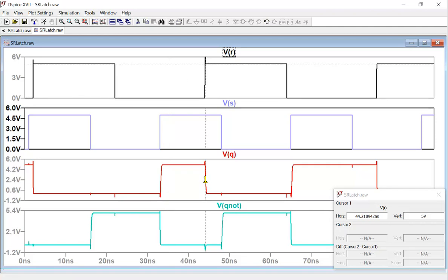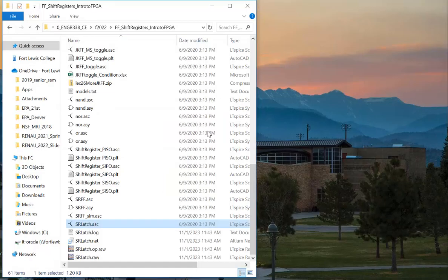Both R and S are 1s. It's not used, but it's going to work. It's just a voltage, right? So 1, 1 is going to give you a 0, 0 for both NAND gates, which is exactly what we have over here. So on and so forth, right? So this is how we verify the logic of SR latch.